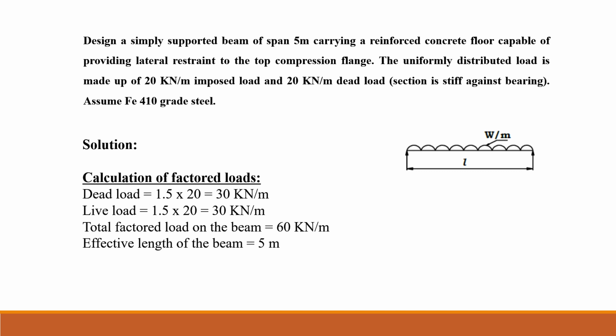Let's see a problem. Design a simply supported beam of span 5 meters carrying a reinforced concrete floor capable of providing lateral restraint to the top compression flange. The uniformly distributed load is made up of a dead load of 20 kN per meter and an imposed load of 20 kN per meter, and the beam's own dead load. Assume Fe 410 grade steel is used. Let's see a diagram.